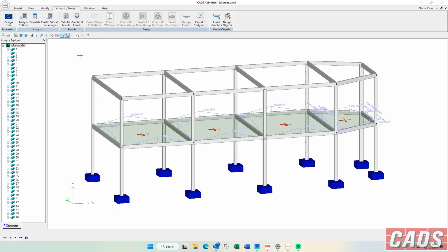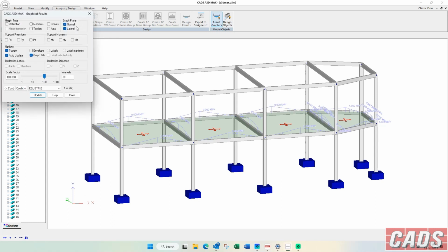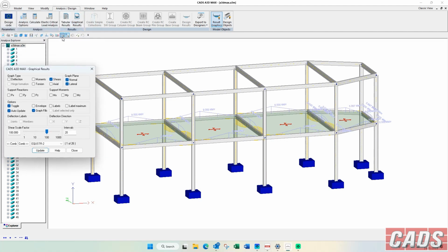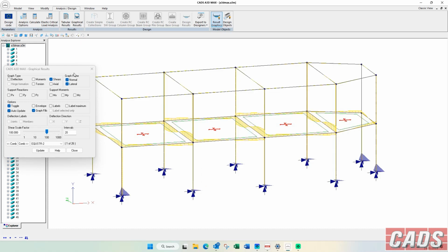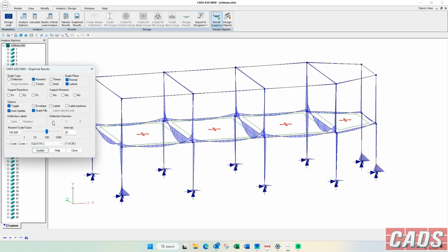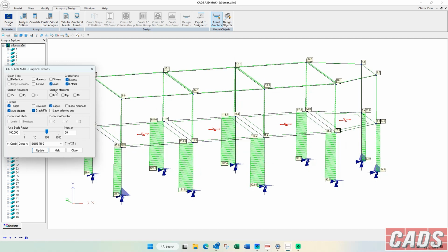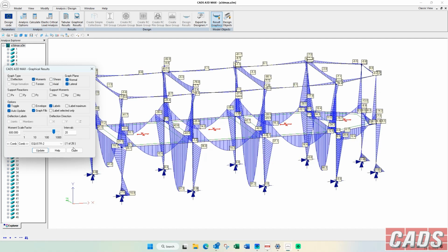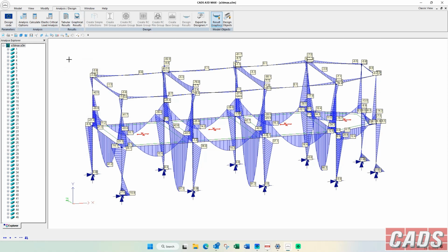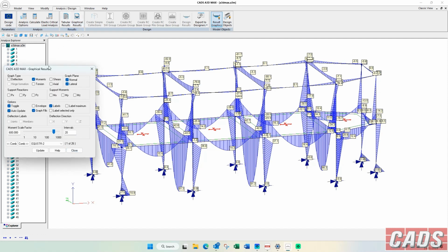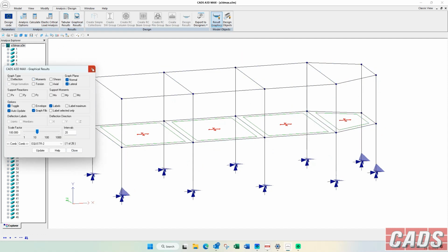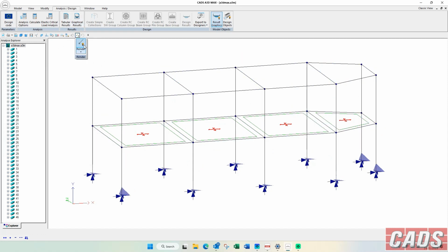There we go. So that's the loads shown distributed. We can go up to the graphical results. There's the bending moment, shear force diagrams. Maybe a bit clearer if we turn the loads off and turn the rendering off. There you go. So we've got the moments, and we can make the numbers a bit bigger. There we go. Actual loads, labels, shear moments. There we go. Very simple. Different ways of doing things depending on which level of modelling you're doing, but all the same, quite versatile.